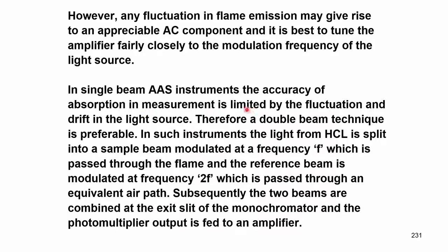In single beam instruments, the accuracy of absorption is limited by the fluctuation, obviously, and there is a drift in the light source, because there is a time gap between the measurements. In single beam, first we put a water sample without any analyte and see the blank reading, the reference reading, and then we take it out, put our sample, aspirate it, wait for equilibrium, and then take the measurement.